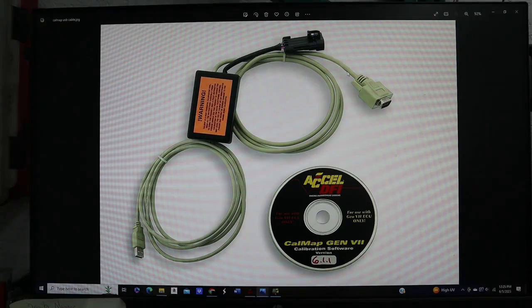If you're getting connection and it's working most of the time, but then you start the car up and it doesn't work, or it could even do it with the key on, engine off, because you may have an electric device like a cooling fan or something like that producing the noise. There's really not a good way of figuring out RFI or EMI.